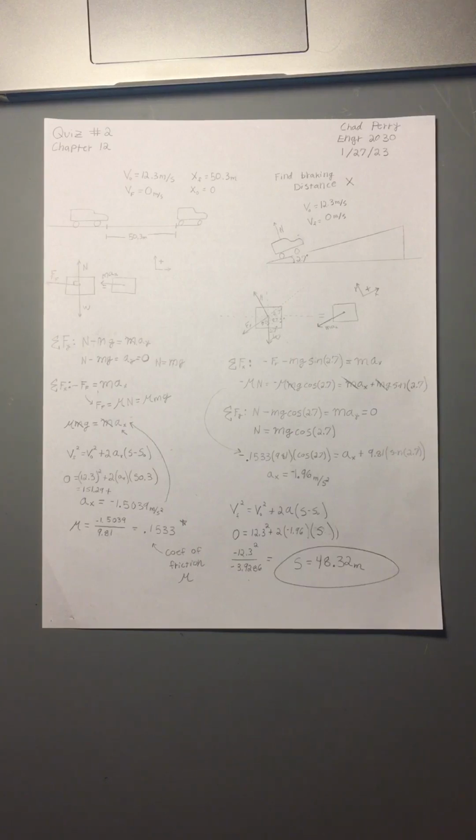So I drew a little picture of what was happening, and then I took that and drew a free body diagram from that. We have the normal force up, the weight down, and then the force of friction from the tires stopping the car. And then that equals our kinetic diagram, where we're accelerating to the left. Then I put the direction for my coordinate system, which I decided to use the Cartesian coordinate on this because there was no circular motion really.